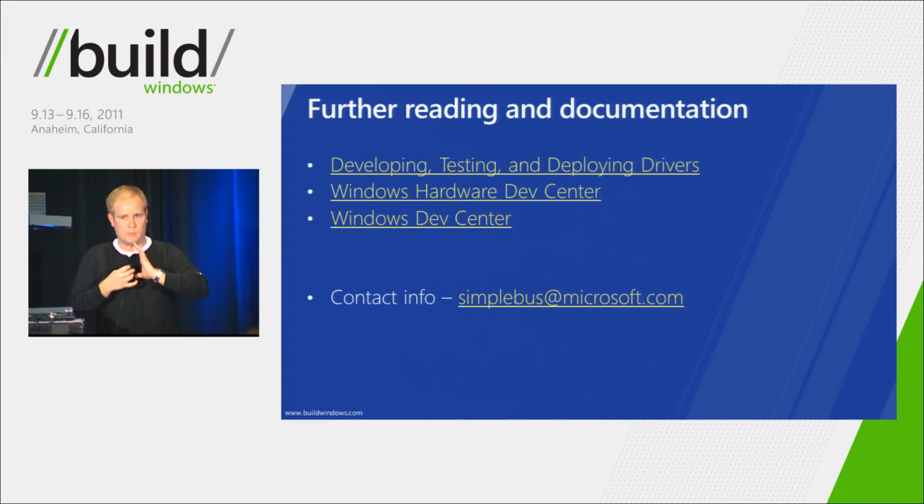There's absolutely a world of customization here, and nearly everything you can think of is possible. Nearly. Don't want to make too many promises. But if you email us, we can help you out with that and give you an idea of who to talk to. But it is possible with ACPI. I can even think of it in my head, where you could hide and unhide a device based on a command, or change the identity of a device. But these are not plug-and-play buses, and primarily should not be. We don't assume that they're treated as such, so we may run into things that we didn't address.